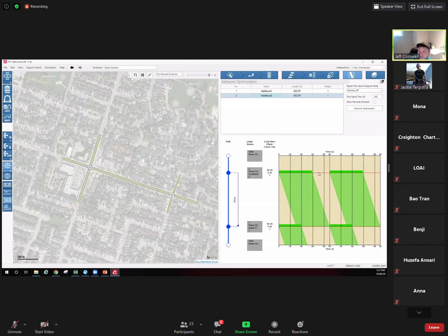So these red lines, right now they show 90-second cycle and they show your intersections. Another reason why it's important to name your intersections here. So it says Stone Church in Cortland, and this one says Stone Church Upper Paradise, 90-second cycle, 0-second offset. So if you go on this red line, you actually get these arrows where you can move these around. So if anyone wants to play around with that, you can actually see how you can adjust your offset. So I've changed my offset to 13.8.